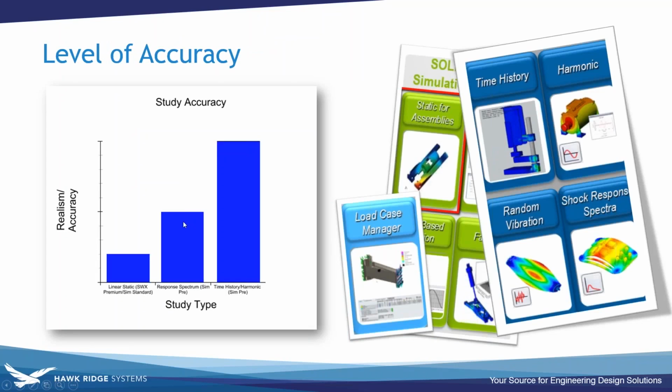Really, again, just to break it down, we started off with the linear elastic study that comes with SOLIDWORKS Premium Simulation Standard. We then define the seismic response spectrum analysis. That is a little bit more realistic because we're inputting what those load conditions are, but it's not going to give us a lot of information like a time history and harmonic study from the other additional dynamic problems will give us, because our inputs are a function of time or frequency, where we can see those stresses at those different time steps.